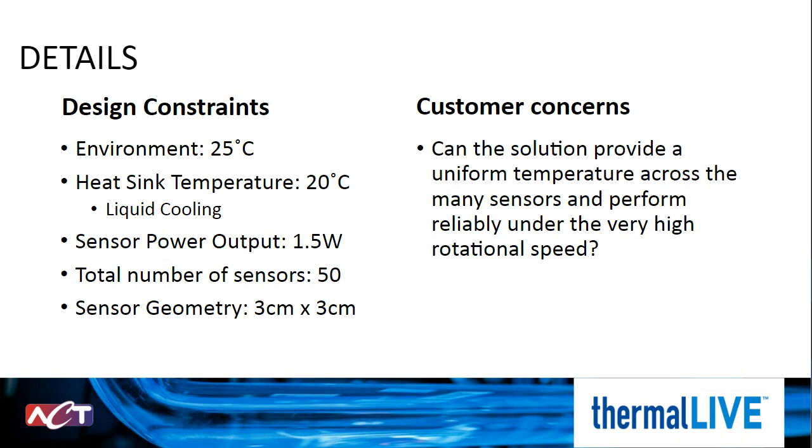At this point, we'll want to know if there's any additional design constraints. Do we need to put it through an autoclave? Now, if it's large medical equipment, we will not need to, but that's something to look at in some of the smaller surgical equipment. Does it need to be processed or cleaned or have a serial number, and how does that apply to our actual design?